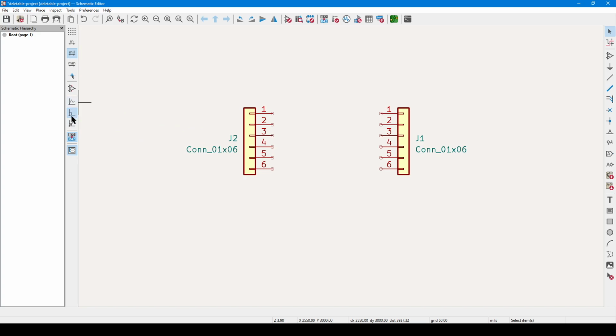From my own experience and in my own opinion, 90-degree mode is the most professional. This mode will constrain your wire direction to 90-degree steps. This makes it easy to stay on grid, and if your schematic is densely populated, it might be easier to read. The free angle mode will let you draw your wire at any angle, but if you overuse it, it can make the design look amateurish.